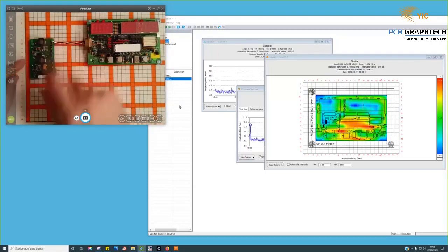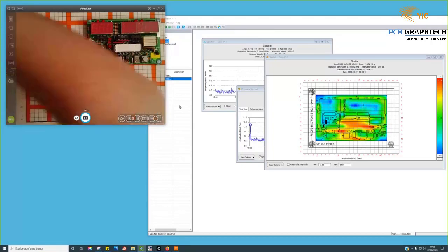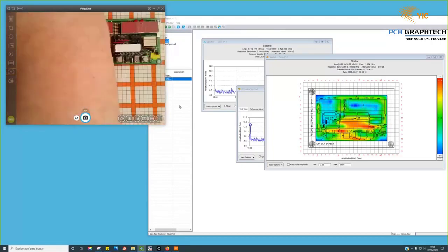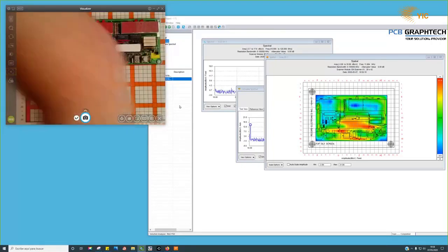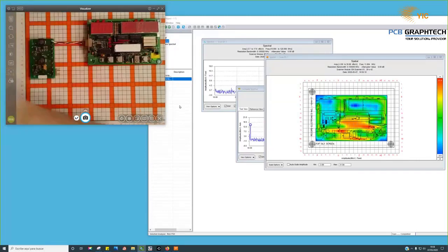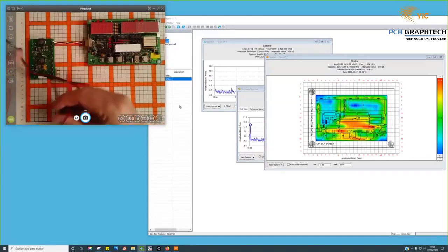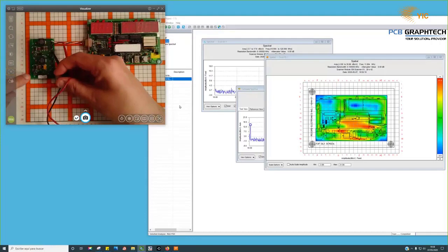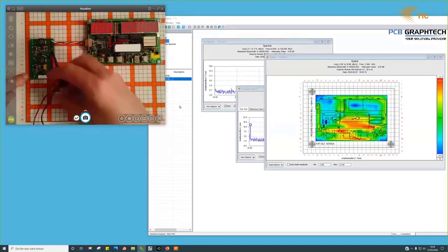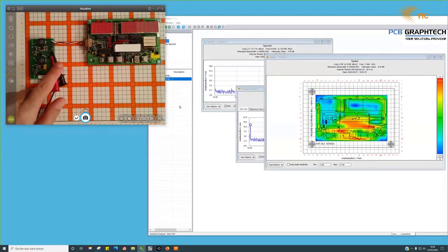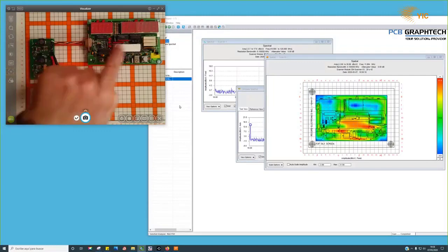And this is the DC-DC converter. Now, the DC-DC converter will take from my power supply a 9 volts voltage that is going to the pins of the PC board. Okay, this pin and this pin. Now this is 9 volts. This is the buck converter with the inductor of the buck converter. This is the cable carrying 5 volts that goes to the microcontroller board.